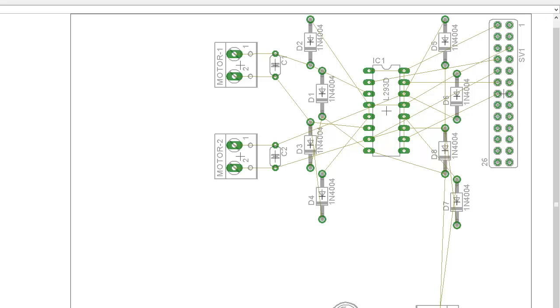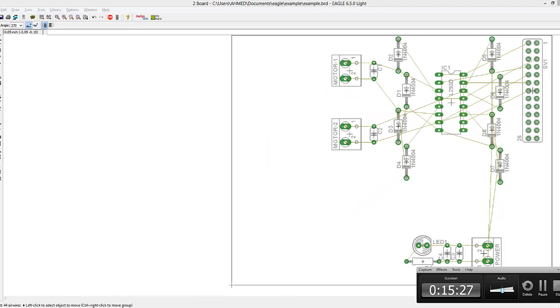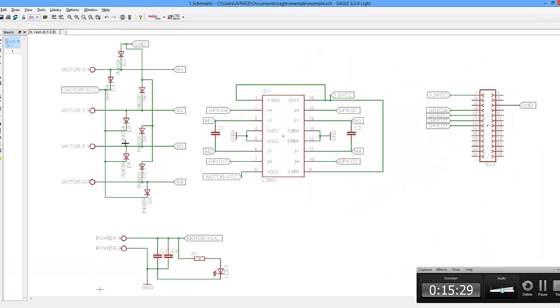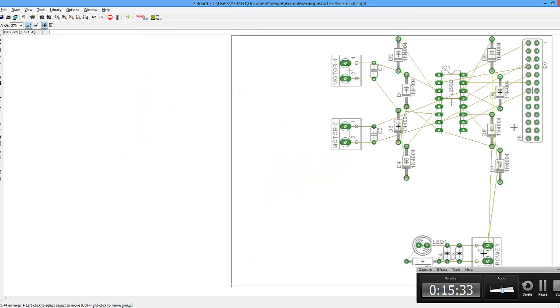Was it D4 and then D3 and line up? Yeah, it was D4 then D3. Oops. Okay, so just move this one up. There's nothing wrong with what I did. The auto router would find a solution, but it would be a horrible solution. So the more you make it easy on the auto router, the more you make it easy on yourself.